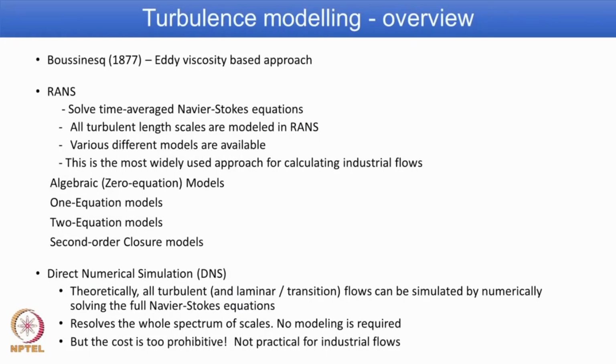So, it resolves the whole spectrum of scales, and absolutely no modeling is required. On the other hand, though it looks very good, there is a great disadvantage. The cost is exorbitantly prohibitive. It is very high, because in order to resolve all the scales, you need to have mesh resolution as well as delta t fine enough. That is very expensive, and it is tried only at academic level, not attempted for any industrial flow problem.